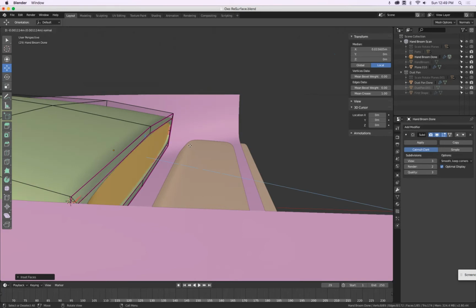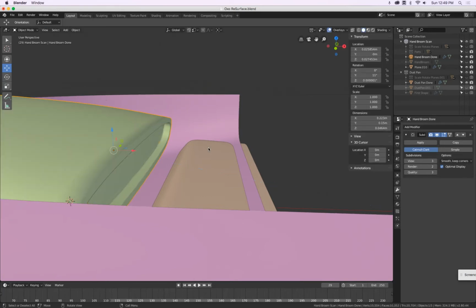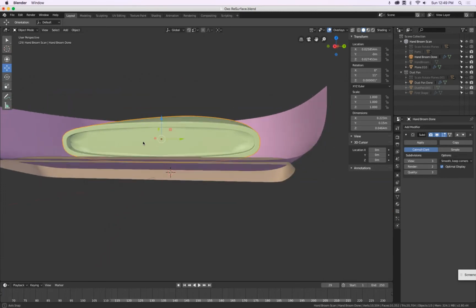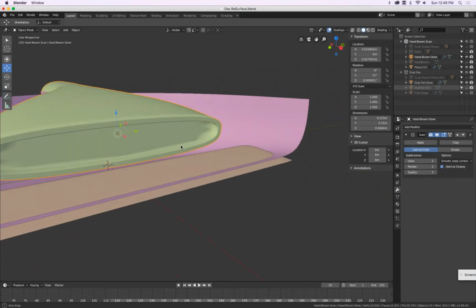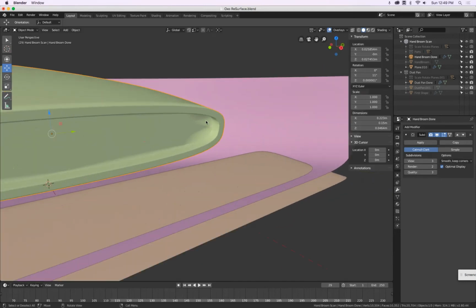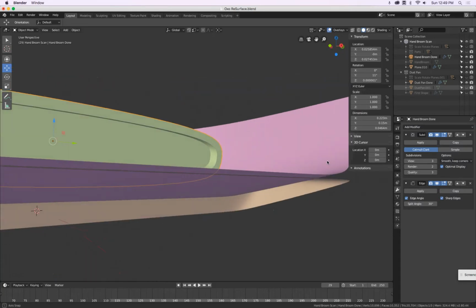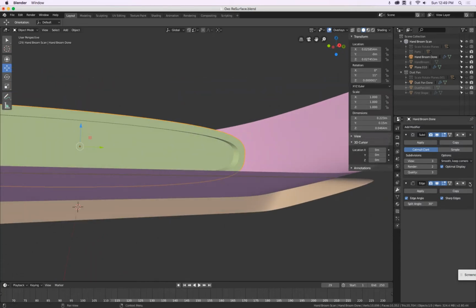And then we press E, and we can do an extrusion to the inside. So you see we just created kind of like an offset thickness and then push the part back. Very nice. These are some shading artifacts. We can fix this by doing the edge split there, nice and sharp. But for the moment, let's remove this.